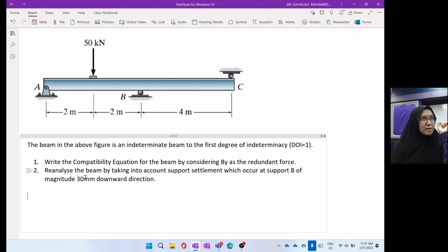That's why, look at the formula for displacement. What is inside the formula? MB, M naught. MB, M naught. So MB belongs to the moment equation in the redundant, BY applied. That is MB. Okay, M naught. What is M naught? Moment equation in the primary beam.